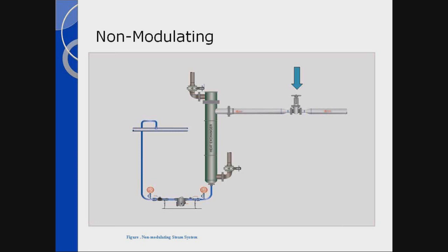That valve is not a control valve. That is an on-off valve. So when the process is operating, that valve is fully open, and the steam is not modulated to the process. In these cases, if you look down at the bottom of the print, where we show a steam trap, P1 and P2, we're always guaranteed a differential across the steam trap because the steam pressure is not modulating. Therefore, the condensate return line that's shown there can be at some elevated pressure, but it has to be lower than the supply pressure. The condensate can be sent back to the boiler plant under pressure.